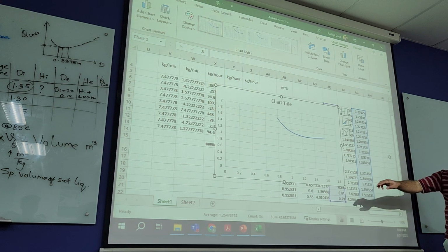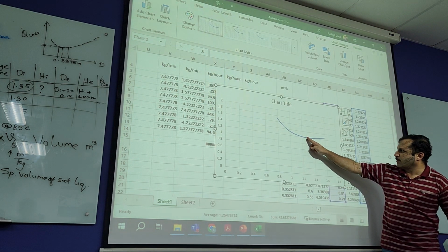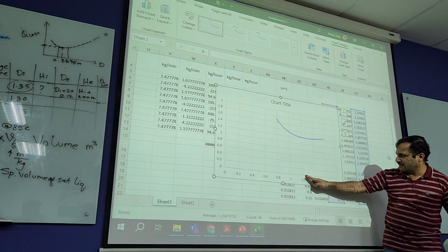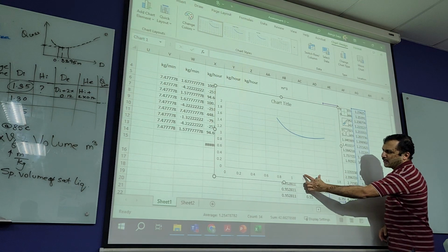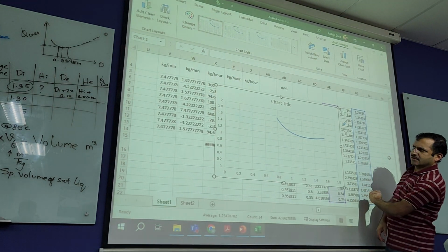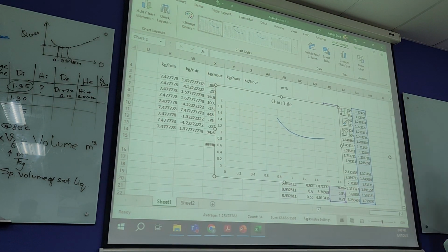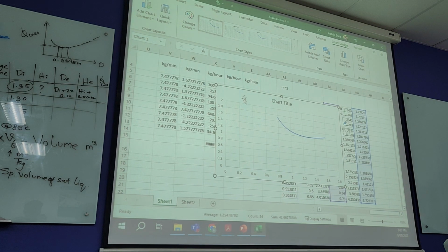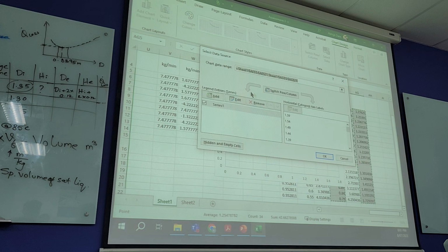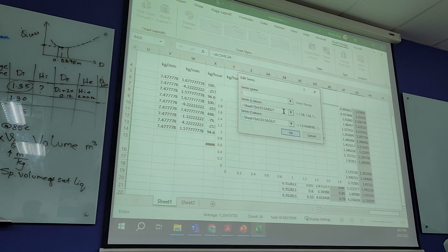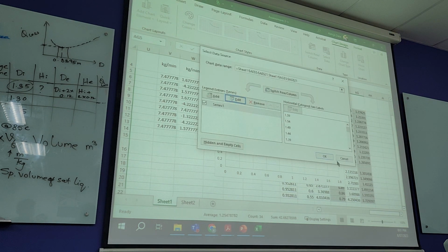Okay, 1 point something. For me, that minimum or optimum diameter is somewhere about 1.3, but I'm going to say between 1.2 and 1. Hold on. Diameter is my x-axis, and heat flux, or heat loss, is my y-axis.